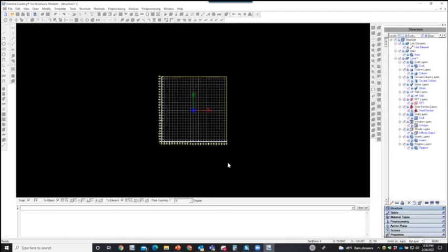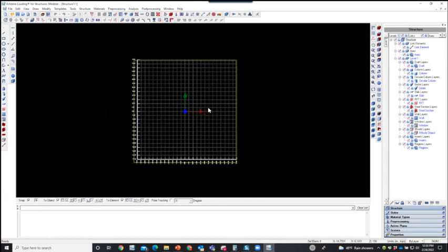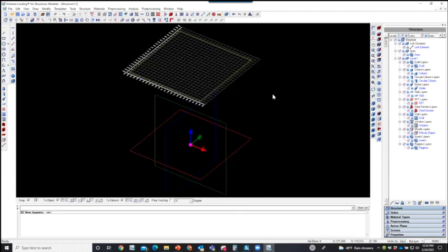This will open up the main modeling window inside ELS, where you have some toolbars for drafting lines, rectangles, every component as you see in the CAD tools. And then we have some components like drawing a column, drawing a girder, a slab, reinforcement rebars, masonry walls, windows, and then the steel members that we need to put. You can model either in the 2D view, as we see in here, XY, or in the YZ.